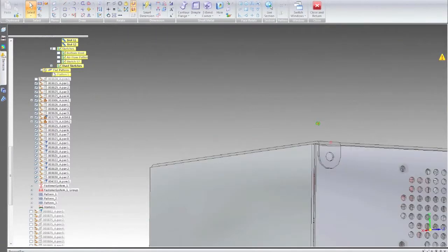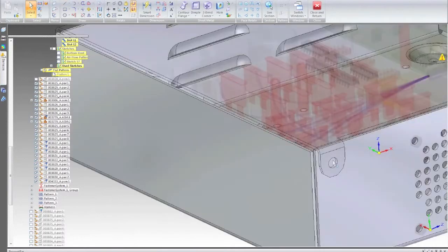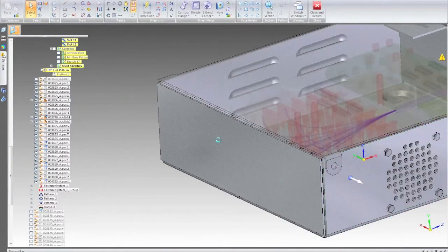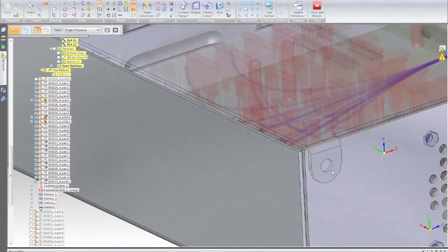Let's see, now my lid right here, I'm going to need a hole right here to pass through this, and what I'll do is we will use the preset. We'll lock onto this plane right here, and what I'll do is I'll use an existing sketch. So I select the wireframe.